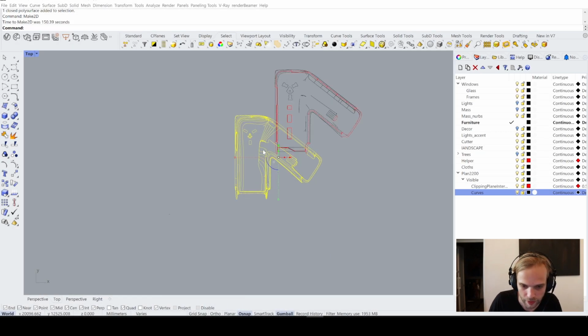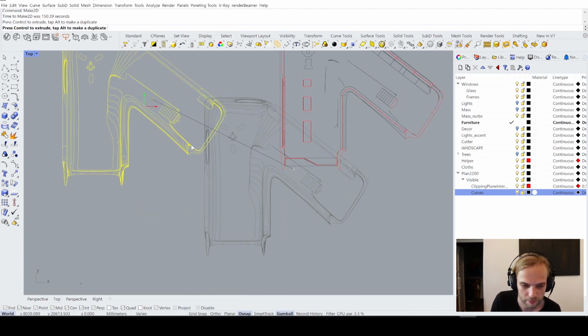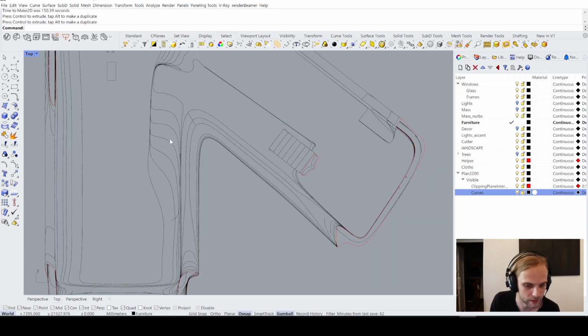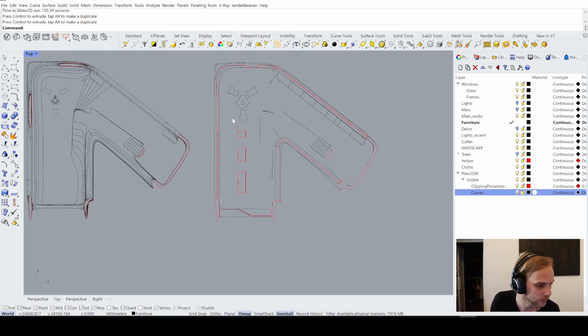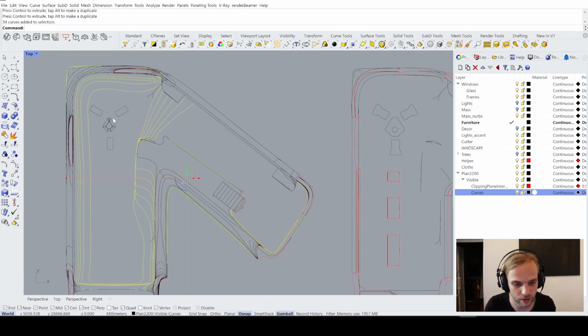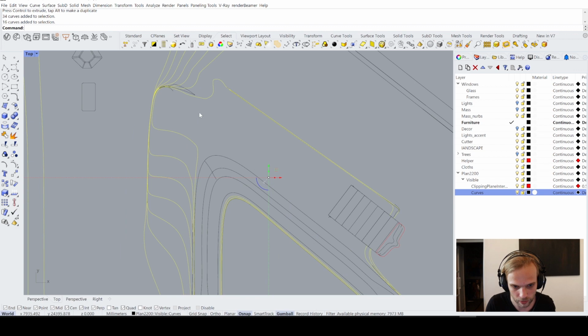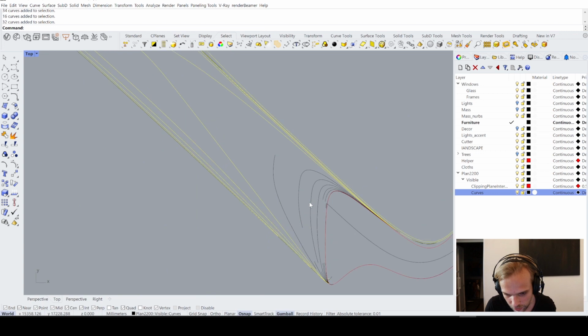There it is. And as you can see right now here, we get quite a few additional contour lines. Not all of them are necessary, by the way, but we can use them on our initial plan drawing, and get a pretty nice additional level of detail. So just to do that, I will be selecting only the contour lines, like that, and this one as well, and we want these guys right here. I'm just kind of going through this.